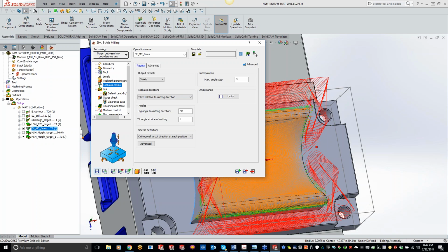And I know Jason, yeah, so that kind of cleared up his. So Jason, to go along the same thing, what I said is switch it over to a bull nose end mill, and you'll eliminate a lot of that. Or you can use the 5-axis and use the side of that cutter, so you're not using the very tip of it. Perfect. All right, cool. Thanks.